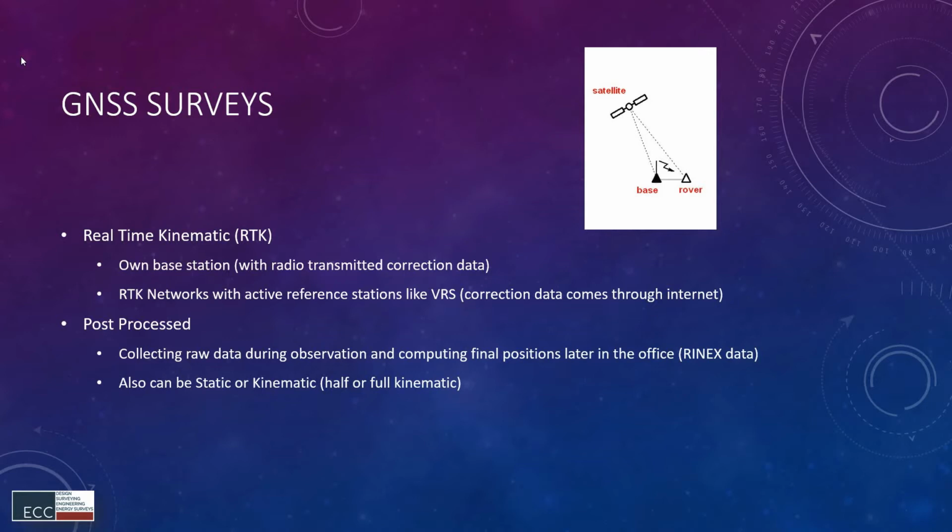But the main theory is that you need a reference point or base point as close as possible to your location, so you have the same circumstances around the base as around you, like the ionosphere and all the satellite positions, so you are receiving signals from the same satellites as the base does. That affects the accuracy.